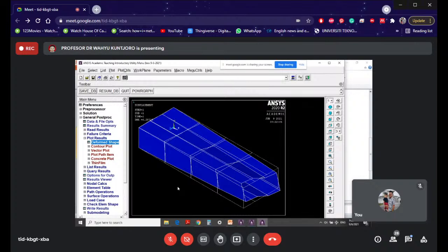Although it looks rather extreme and drastic, actually the deformation is small, because if you look at the maximum deformation magnitude, it is only 6 millimeter, 6.2, 6.3 millimeter. Remember, the length is 3,000 millimeters, so 6 out of 3,000 is not much actually. So this is exaggeration, of course. It looks a kind of bending up and also twisting because of the applied load.